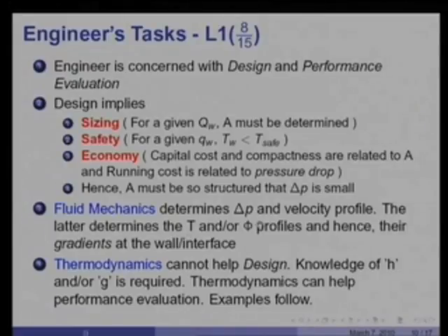Fluid mechanics determines the delta P as well as the velocity profile, and the profile in turn determines the gradients of temperature and phi profiles at the wall, which enables you to calculate h. Note that thermodynamics cannot help design, simply because thermodynamics deals with the change of state and not with the rate of change of state.